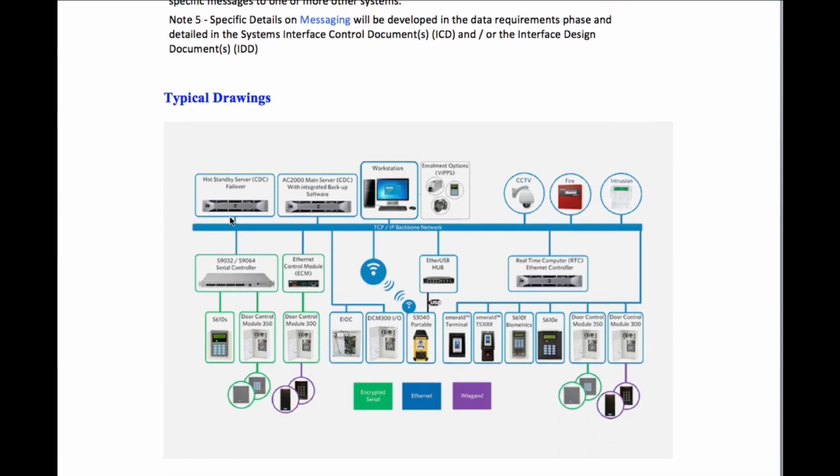So that's why it's very important when you write your specs that you prepare something similar to this yourself in your specification, so that you can put all those interfaces on this drawing, a simple system drawing, and all the interfaces to others, where you can very clearly define what this guy has to do and what his obligations are under his contract.